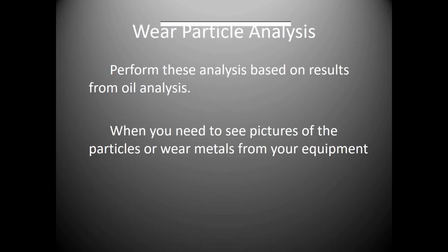This is what we want to see. What are those particle counts? They're high. We might know they're iron, but this is what it looks like. I can tell you we have some high bearing wear or high gear wear when you start getting pieces off that are that large. So again, wear particle analysis is more expensive than oil analysis, but it gives us that physical view.